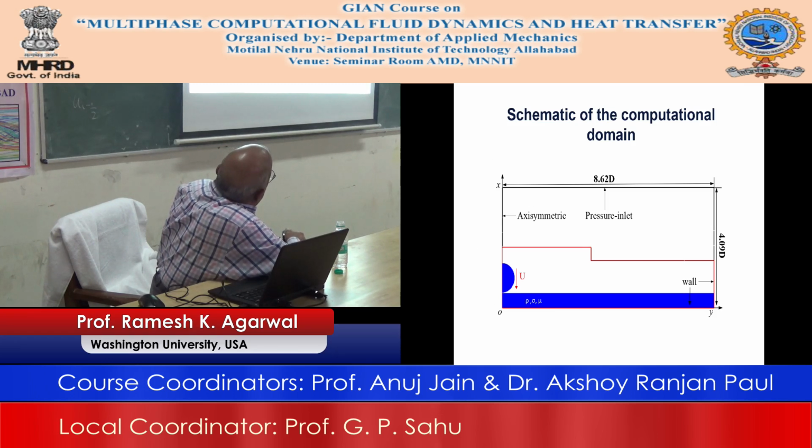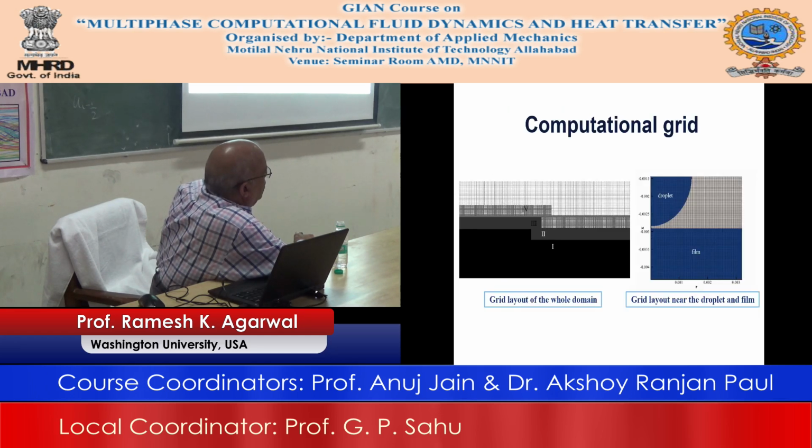So this is the velocity u with which this is impacting this film, and then this is the grid. It turns out that the grid has to be very, very fine in order to have a grid independent solution. So this almost looks like a black area which is full of grid, and then this is a relatively coarse grid. You can see the grid getting less and less coarse, and very close to the bubble, this becomes a very coarse grid.